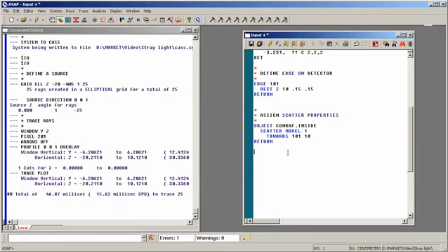Let's put our rays into our system. Define source. Grid elliptic Z, again, it's at Z equal minus 20. That's the entrance to our system. It's a semi-diameter 6, so we're going from minus 6 to 6 in X, minus 6 to 6 in Y, 1 ray in the X direction, just for simplicity, and 25 in the Y. Source, direction, 0, sine 20, cosine 20.